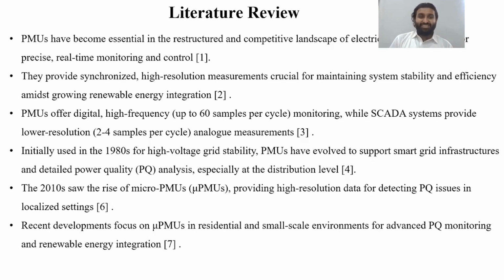PMUs offer digital high frequency measurement, up to 60 samples per cycle. This is a little different from SCADA, because SCADA provides lower resolution, just 1 to 3 samples per cycle, and also has analog measurements, but a PMU provides 60 samples per cycle. Initially used in the 1980s for high voltage grid stability, PMUs have evolved to support smart grid infrastructure and detailed power quality (PQ) analysis, especially at the distribution level as well.